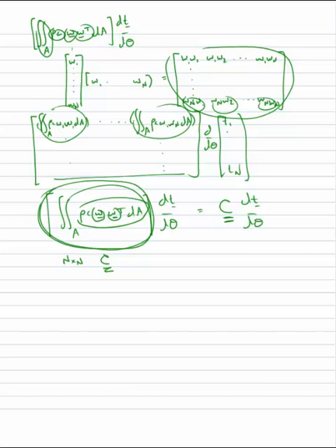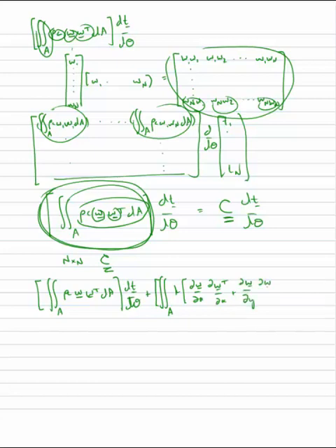So if I write this for all of the terms, what do I have? I have the integral over the area of rho times c times w transpose dA times d temperature d theta, plus the integral over the area of k times dw dx times dw transpose dx plus dw dy times dw transpose dy times dA, all multiplied by T, equals, on the other side, the integral over the boundary of W times the heat flux normal ds plus the integral over the area of W times G triple prime dA.